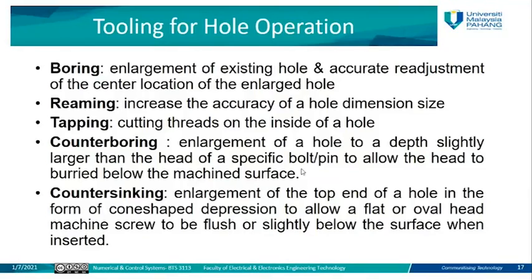Also countersinking here is used to enlarge the top end of the hole in the form of a cone shape. That means it will make the end of the hole in the shape of a cone, not like the flat end. Also it can be used to sit flush slightly below the surface when inserted.